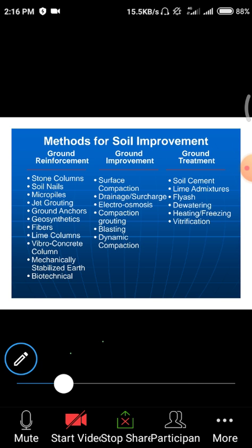That means, for example in hilly areas, the top layer will be grouted with the help of cement concrete paste. Some amount of external additives, admixtures, and super plasticizers are used for rapid hardening of the concrete paste. This kind of mechanism is normally called grouting. For this grouting, we need high-rise mechanized equipment. That means we need to pump with a certain amount of force, so we need mechanized equipment for force pumping of this concrete and cement paste.